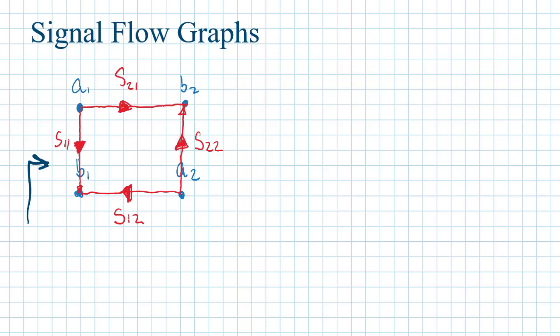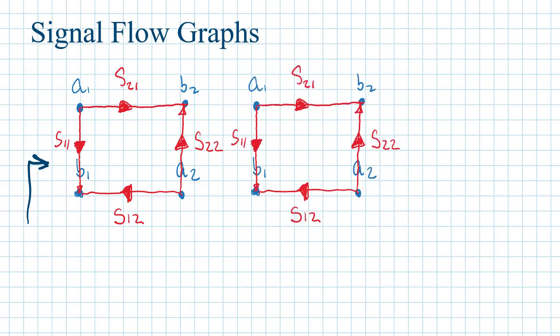So to represent a second S parameter matrix, we can just drop another copy of the existing one and slide it in next door, and we'll just connect them together. So we have a second two-port S parameter matrix represented as a signal flow graph, and we'll cascade them by, just like I said, just hooking them up together.